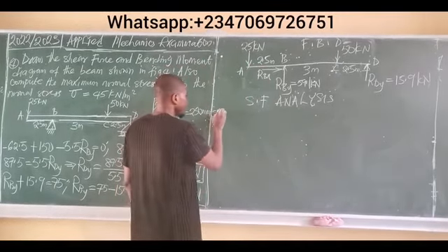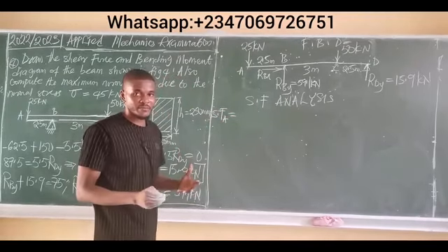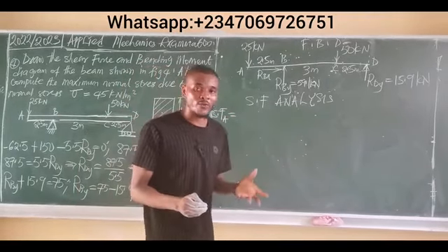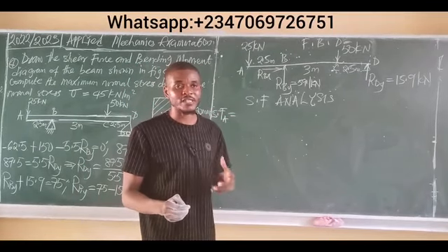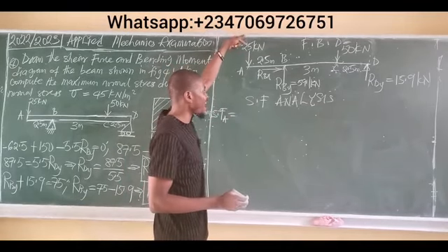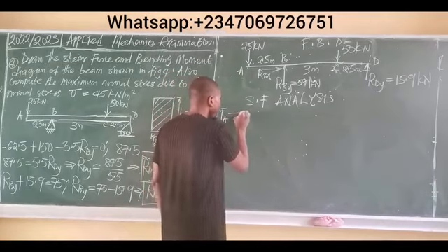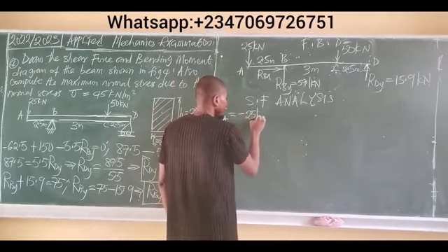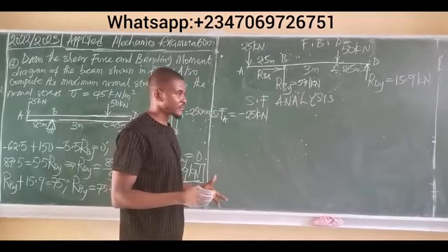Shear force at A simply means the force that exists at point A on the beam. Now, is this force an upward force? Then take it as positive. But if the force is a downward force, consider it to be what? Negative. And at point A, we have 25 kilonewtons force acting where? Downwards. Since it's acting downwards, it becomes minus 25 kilonewtons. Consider it always as negative.